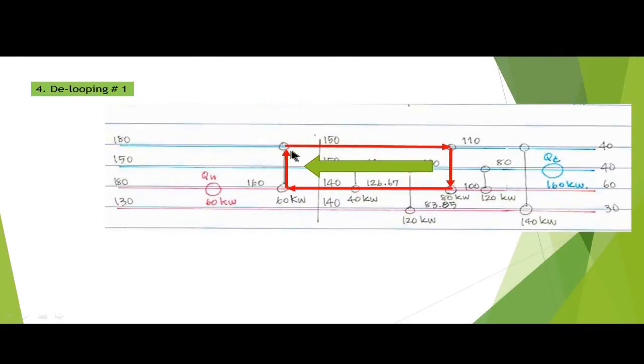So in this case, if I combine these two heat exchangers together and get one, it means you have heat transfer between these two regions. If we have heat transfer between these two regions, the heat utility and cooling utility will be changed because of the interference based on pinch consideration. So what we do,